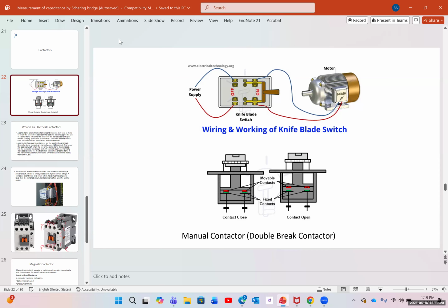Another thing is that contactors act like a protective system. Some of them have a heat protection system and a current protection on top of that, which acts like an extra layer of protection, like a fuse on the motor. If something goes wrong, like the motor is under pressure, it heats up, or you have too much current or too much voltage, the contactor would disconnect. The worst case scenario, you damage the contactor, which is $20, instead of a motor, which is sometimes $5,000 or $10,000. So it acts like a protective layer for the motor itself.